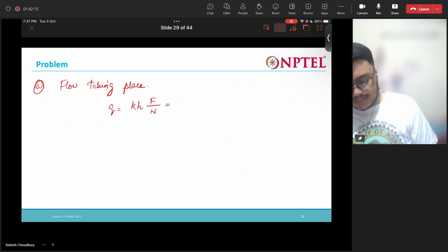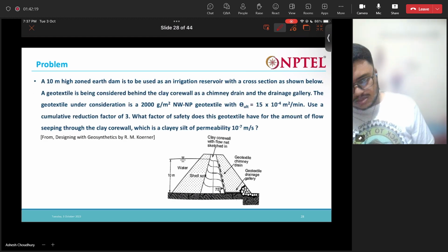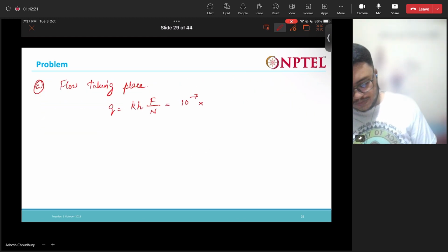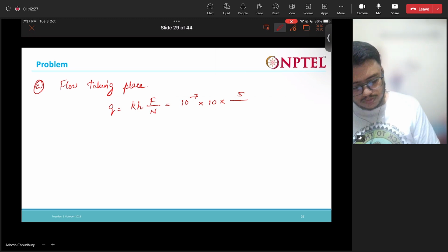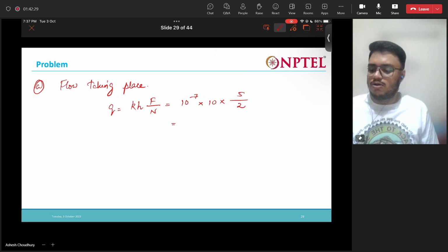What is k? It is 10 to the power minus 7. H, what is the head? Head is 10 meters. Number of flow channels is 5 and number of drops is 2. Let's calculate this.